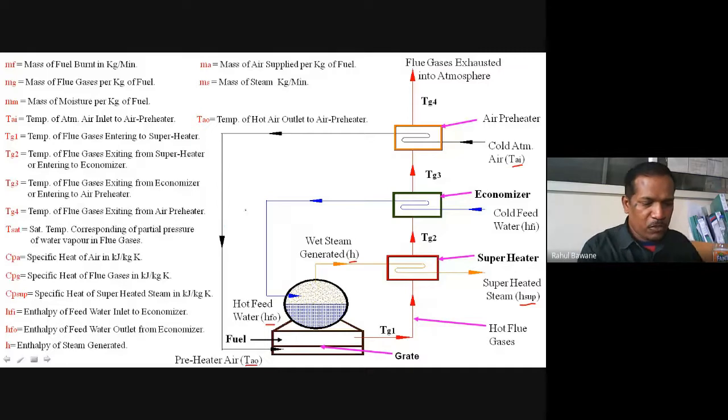Now, when we talk about a heat balance sheet, it must have some standard format. The balance sheet has this kind of tabulated format. Whatever your calculations are, your final answer should be in this tabulation format, where at the top it says it is a heat balance sheet and it is divided in two parts. One is the heat supplied, so heat energy supplied, and then its unit, kilojoule per minute.